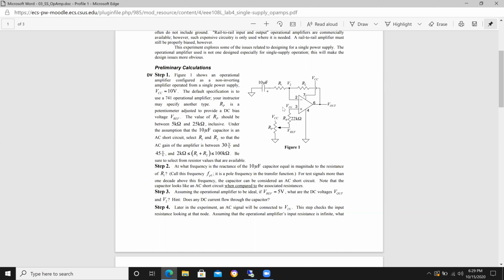So you got the capacitor coming into the circuit. The frequency has to be high enough to where that capacitor is closed and you're coupling the signal coming in. Then the other condition that has to exist is in your feedback network. The frequency has to be high enough such that this capacitor acts as a closed switch across here, right? And by closed switch, what I really mean is that the impedance of the capacitor at a given frequency is negligible compared to these other resistor values, okay? That's often referred to like going above and below the pole frequency, which is typically a defining moment, or a metric for that, I should say.